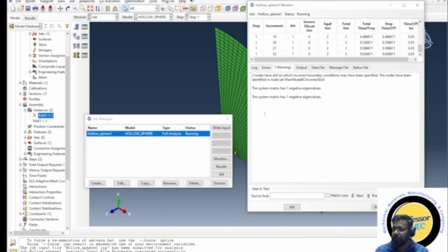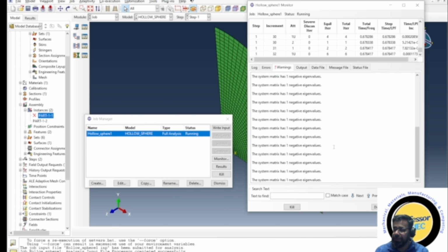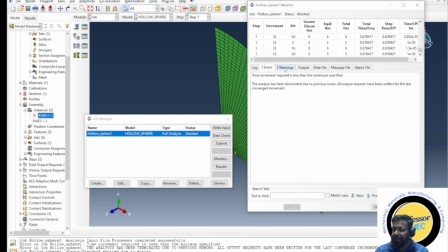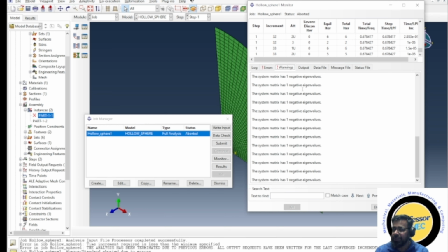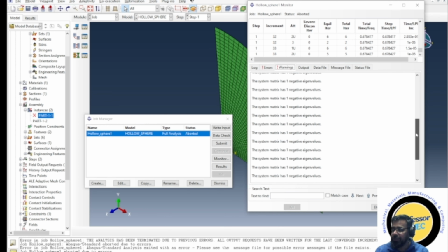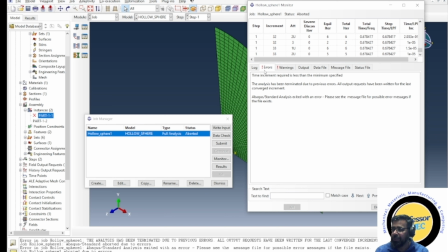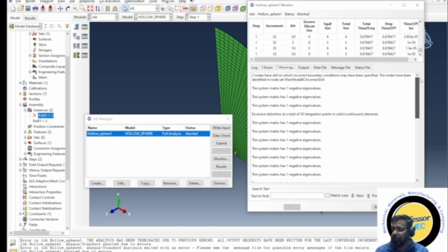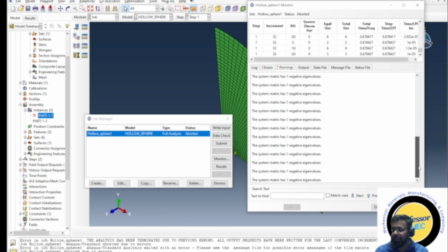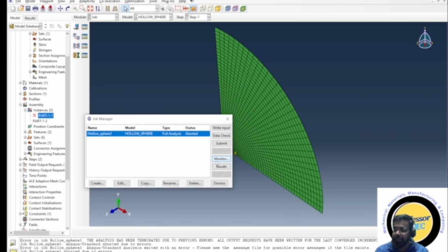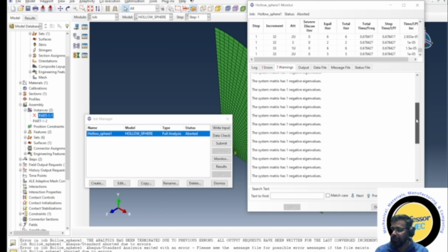In this, okay. System has, I think your material properties might be the problem here. And that could be because it's again we're going to the same point and then it gets stuck. But you see that numerical singularity thing is gone because we have removed the other geometry, because that was moving around everywhere and there was no constraint to it. But these negative eigenvalues are generally because of the poor mesh or due to the material properties. Now I don't see that error which you are mentioning.